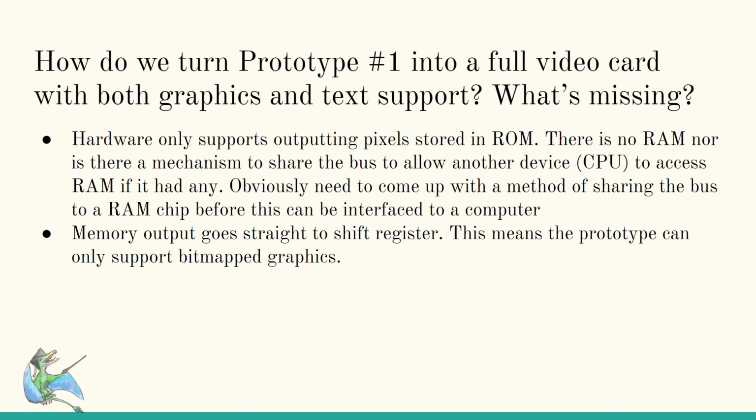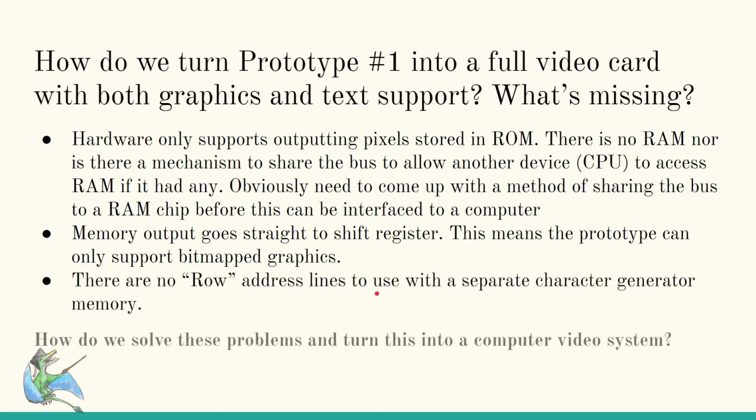That's what you need when you have basically anything that's driving the address bus, what you can call a bus master. When you have multiple bus masters that want to share devices, you need to arbitrate between them. So we have to add some external glue. Hypothetically, if we had a much faster MCU, we could play tricks like changing those ports from an input to an output, but we can't do that. This machine is not fast enough.